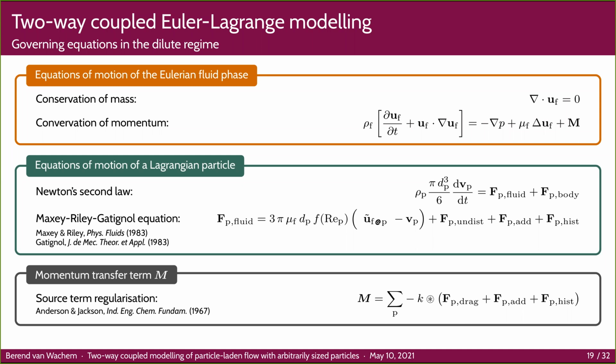I think at the moment the collisions we understand fairly well, so we can have hard sphere and soft sphere models, and I think for spheres in a fluidized bed that's quite accurate. Obviously, if you're looking at a fluidized bed with straw particles, that becomes a very different story, because then the shape is so non-spherical that it starts to dominate. But if you look at particles which are more or less spheres, then I think indeed the hydrodynamic approximation is the problem. Yeah. Thank you.